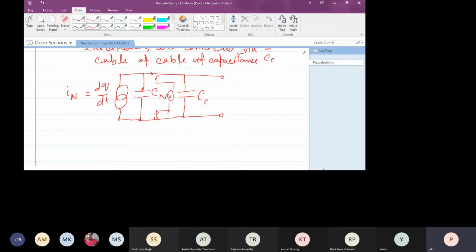So therefore usually it is connected through a cable, and the cable is wrapped with a ground wire, and then again an insulator. So a sheath kind of thing. So two wires, then one insulating sheath, then one ground wire, and then another insulating sheath. That ground wire is grounded at one end.